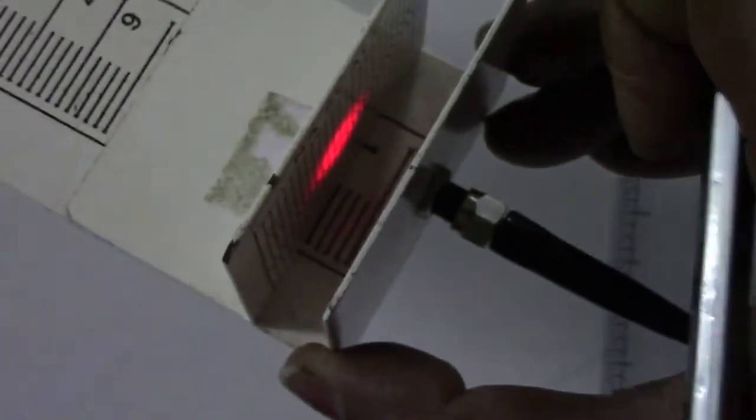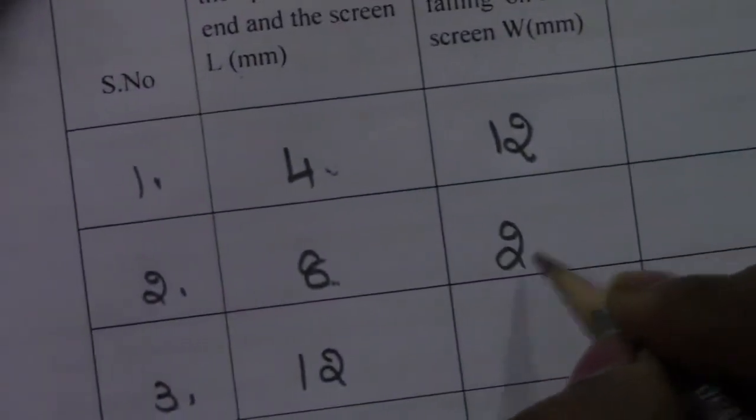Now likewise you need to go for the second reading. How can you take the second reading? I already fixed L for 4 mm, so for the next you need to move your numerical aperture scale on the jig for 8 mm. That means exactly you need to place your scale on the 4th line. 8 mm. Again at this moment you observe how many circles are occupied by the light intensity. So count the number of circles and write the diameter of the circle. So this time 1, 2, 3, 4, 5. 5 complete circles are occupied here. So 5 4s are 20.